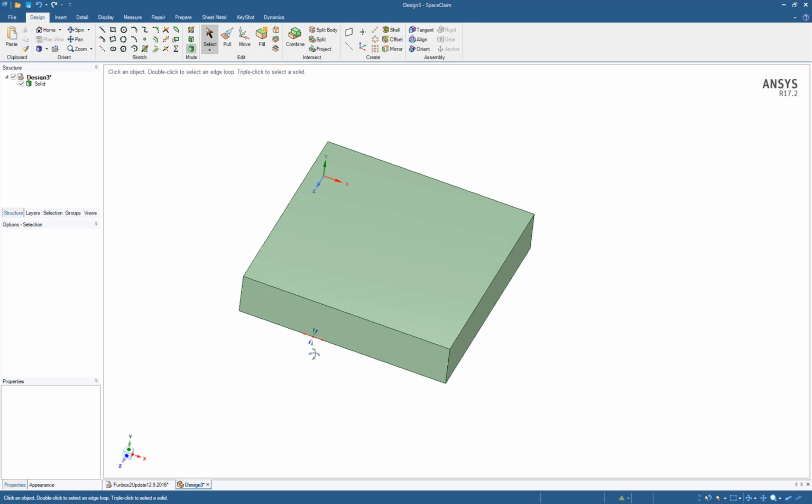Okay, now going off of the dimensions that I wrote down from the other design, I'm not going to flip back to the other design because we already looked at it. What I want to do is divide this face up into multiple surfaces. That makes it easy for me to choose edges and surfaces that are within the larger footprint to be able to make those changes. So the first thing I want to do, if we remember the ramp section, we measured that ramp to be 6 feet on the floor. So what I want to do is split this top surface so that I have 2 surfaces. So instead of being 15 feet, I'll have one section that's 6 feet and the other section is going to be 9 feet.